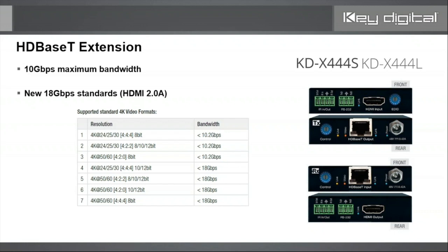Why? HDBaseT, which everybody was using, and it's reliable and it's everywhere, HDBaseT itself was designed around the 10 gigabit per second bandwidth. And so your new sources, 4K, 60 frames per second, 444 chroma subsampling, they couldn't output that content and be extended over an HDBaseT.